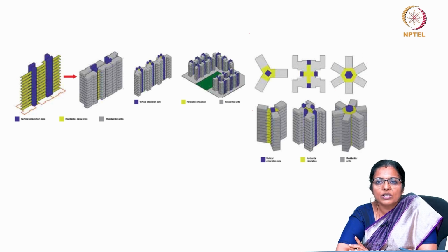So built form which is designed such that it is self-shaded through massing or articulation, resulting in sheltered built forms that cut off a large amount of direct solar radiation, is most appropriate for hot and dry climate. In the hot and dry climate, the envelope should be designed so that it remains shaded for greater part of the day. The external walls should be so planned that they shade each other.